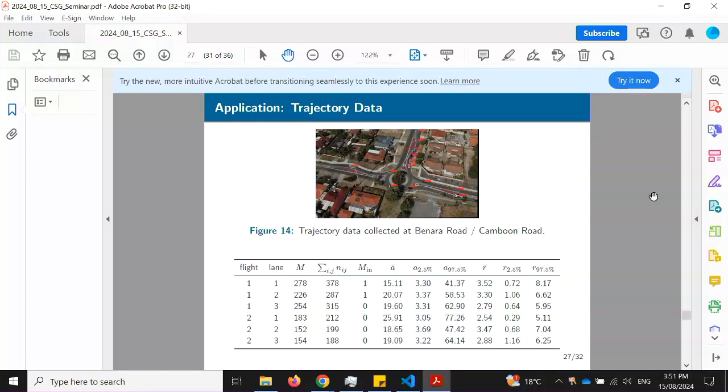So I did try to look into that, and checking the data quality is a bit trickier, especially when you have bigger roundabouts with 2 lanes. When we try to calculate all these gap acceptance available times, you need to find how far vehicles are away. If you have 2 lanes next to each other, sometimes there's false identification saying this guy accepted a 0.02 second gap, but in essence, it's just 2 vehicles entering at the same time. So there are issues with the data, and that's one of the reasons why I decided to stick with single lane roundabouts.